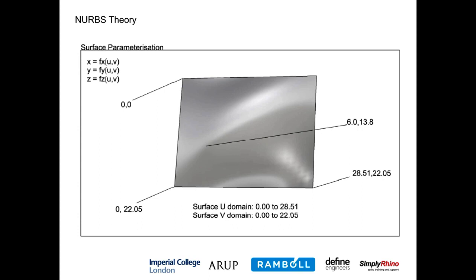So rather than having one single parameter value which you can use to select any particular point on a surface, you instead have two, which are typically called U and V. You can think of these surfaces as being a bit of graph paper with their own local axis system drawn on it. If those two axes on the graph paper are marked U and V instead of X and Y, then you get an idea of how that works.